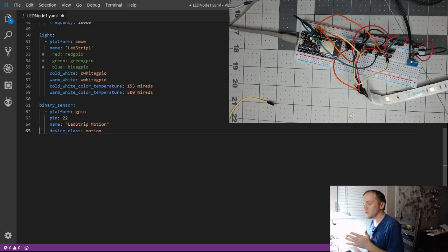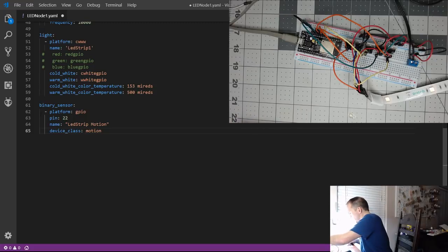The ESP32 is really, really powerful, and the price of them has come down a whole lot. I know there is a Tasmota fork of the ESP32, but I don't think Theo keeps up with it. I think someone forked it, and it doesn't have all the features. So if you want a good solid ESP32, ESPHome is the way to go. It's real simple to do.